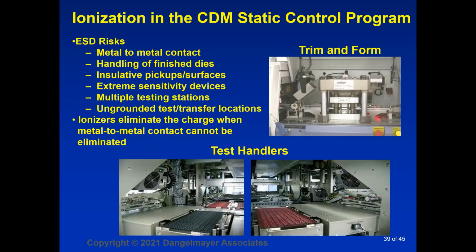We have contact and separation of different insulators. Is charge going to be generated on the socket? Most likely it will. So now you have charge on the socket. An uncharged product comes in, but the charge on the socket induces a voltage on the pins, and you get ESD when they get inserted into the socket.